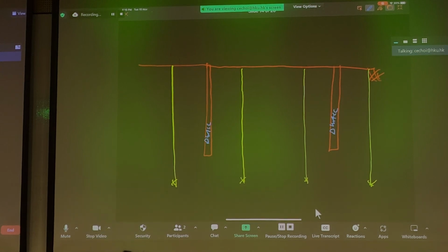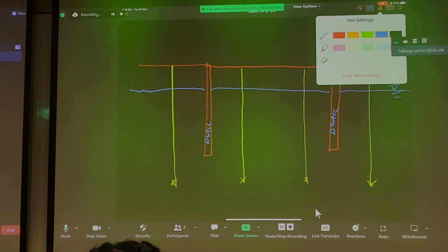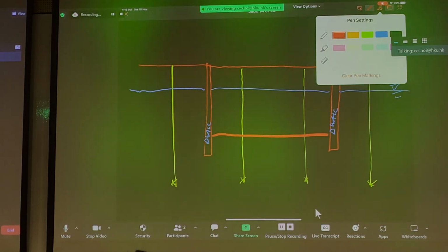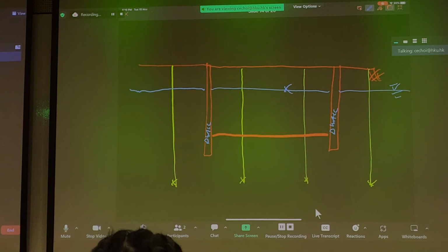So let's say the groundwater table is initially hydrostatic like this, but we need to get to final formation level in the ground, let's say here. That means we need to somehow suppress this groundwater table to perhaps some elevation below the working elevation, so we can work and have machines inside. Otherwise, the excavation will be submerged.